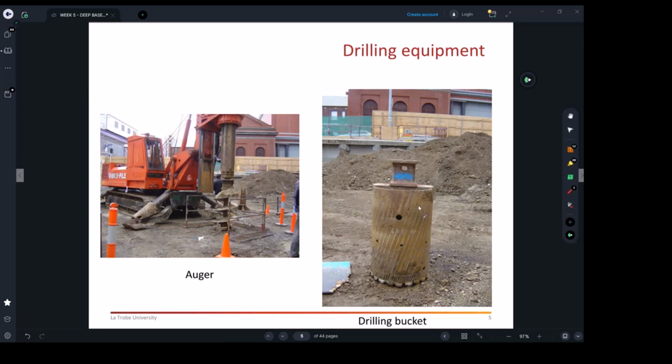And don't expect that you're going to excavate and then pull it out, because the soil will collapse again. We're going to put some shielding around it to retain the soil temporarily. And then when you reach that stable soil, the clay or whatever material which is cohesive, you start using something like this and dig below that 1 meter or 1.5 or 2.